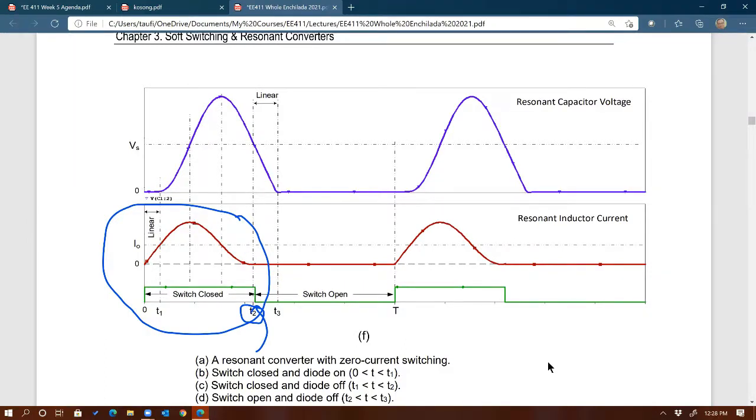If the resonant period is too long, or not too long, but not the right value, then if you want to turn the switch off right there, you can see it's not zero amps, right? So you have a different sine wave that takes longer, meaning the resonant period is longer, right? That means that's not going to work, right? But the answer I was looking for, which we didn't discuss last week, was the first answer.